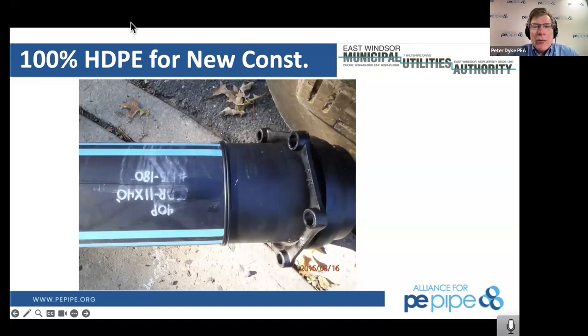Tell us about that. How does that work? Yes, when they do the installation in any of the butt fusion, they're required to put their I think it's their license number on there, stuff like that, so that if there is ever a problem or a failure, we know where it was and who did it, so we can go back and find out. We also use a data logger on all of our butt joints, so that tells us everything out in the field anyway.